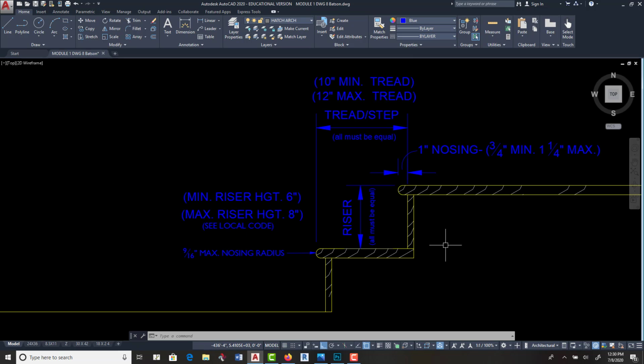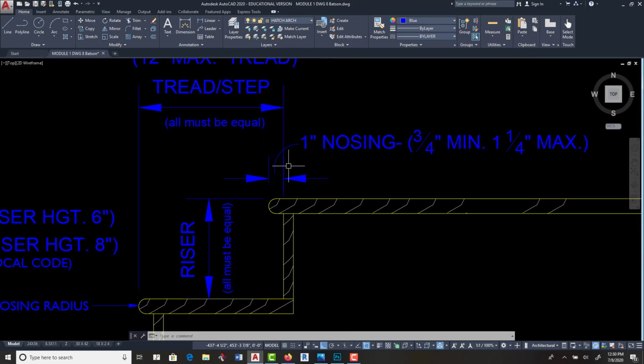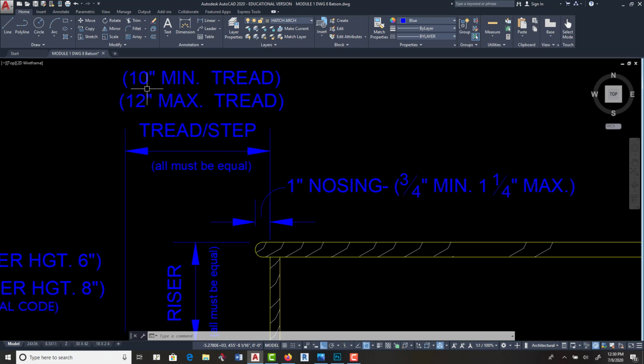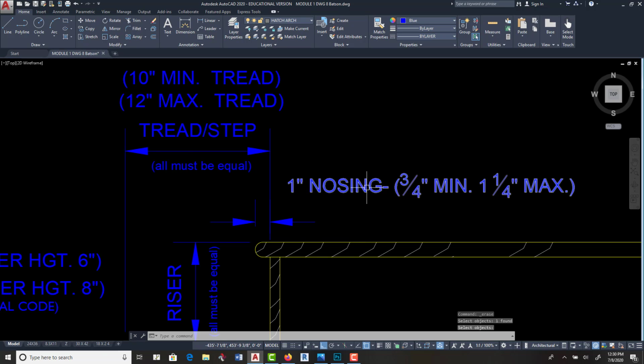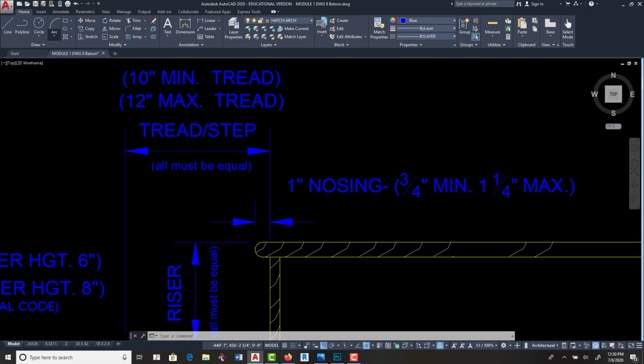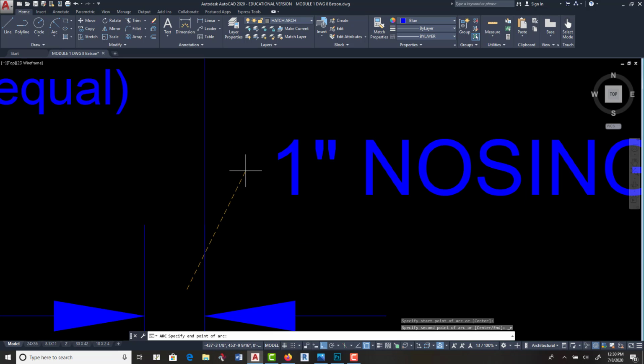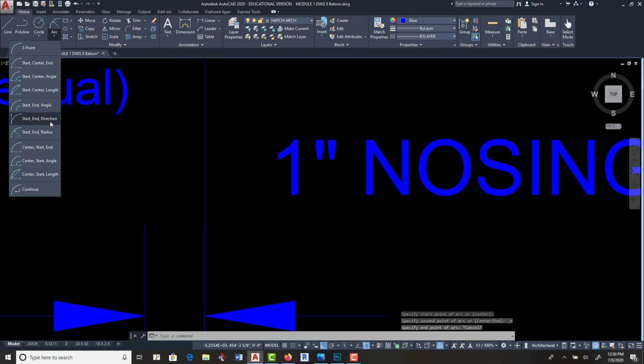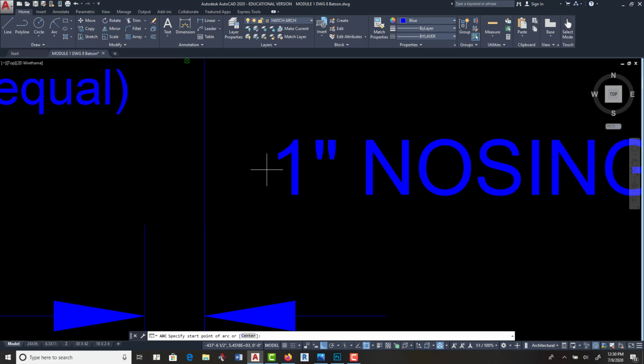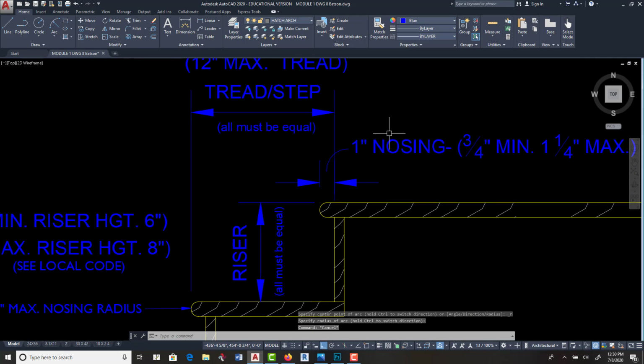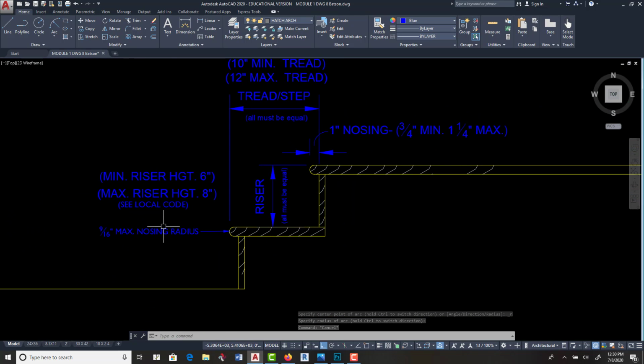Now, your leaders here, sometimes in order to get this line here, you've got to explode it so it becomes outside of its pieces parts, and then you go to arc, start, in, radius, and remember it's always counterclockwise. Okay, take my ortho off, start in, and then you can make a radius that makes it look like, so now we know that's touching here. Sometimes you can explode it and change it.